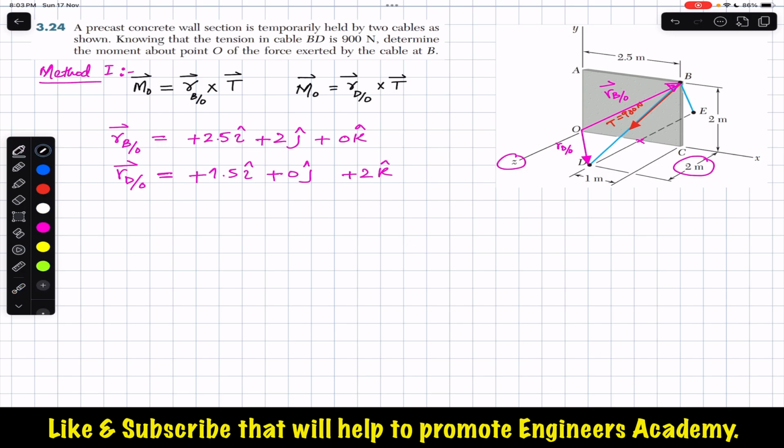So we can say that the moment about point O, using this equation, is equal to, so we can always use the determinant method. So in the determinant method, we will write i, j, and k. And the second row will be the components of this vector. So the components of this vector are 2.5, 2, and 0. And the third row is the components of the force or the tension. So this will be Tx, Ty, and Tz. So before applying this determinant, we have to find the tension T in this BD as a Cartesian vector.